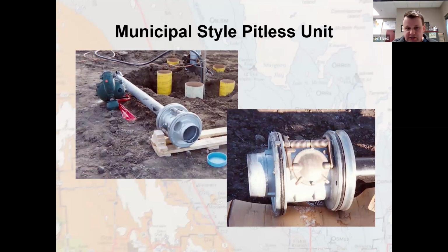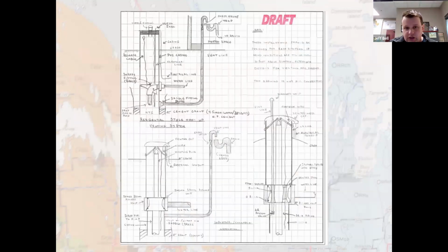And you can see in this picture on the left, you can see that large sort of void right there. That is a pass-through that allows for the wires and stuff to go through it. It also allows air to get down into that well to allow that to take the space. So when you're pumping a water well, you have to make sure that you properly vent it. So in a lot of cases, you have to put in a secondary vent to a water well to be able to get air into it.